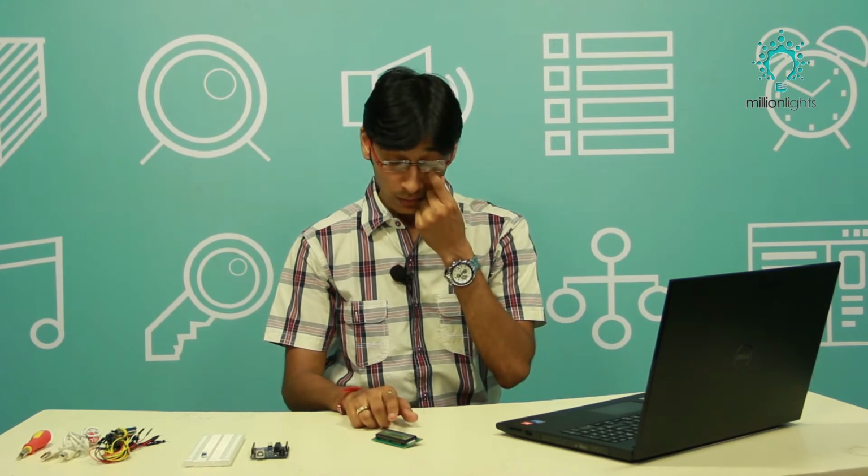So there are two types of instructions from Arduino to this LCD, or from any controller you can take. One is commands and the second one is data. The data that you want to print is 8-bit ASCII code, and the next thing is commands. Commands like you want to print on the first row or second row, at which place, whether you want to blink the cursor or not, scroll it to the left or right, or clear the LCD. So there are a lot of commands that we need to give.